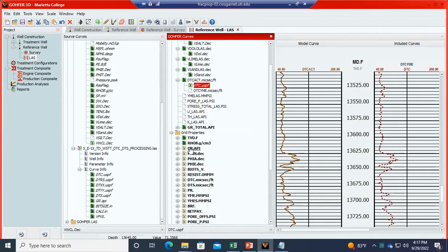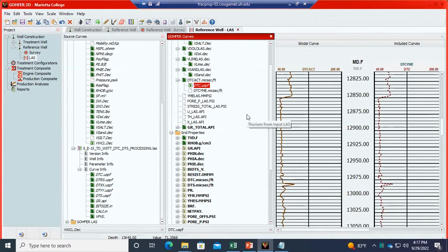Let's remember together how to create the geomechanical parameter. Simply, the Young's modulus and Poisson ratio are calculated using the equations from the dipole sonic log, from DTS and DTC. If you don't have this data, you can use different logging techniques to get it, but it will be less accurate simply because it's a correlation, not a calculation.